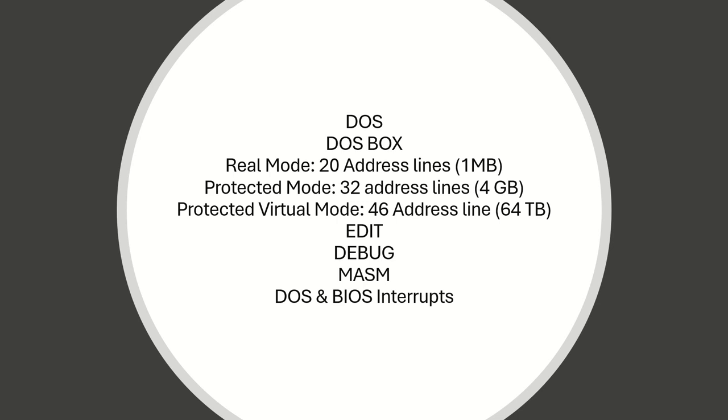Interestingly, when we study any microprocessor, whatever is the number of address lines it is having, we say that is the addressing capacity. So the number of address lines always determines the depth of the memory, and the number of data lines always determines the width of the memory. Let's say, for example, if you look at the first popular CPU, though it was not used in computers, it is still an 8-bit CPU,